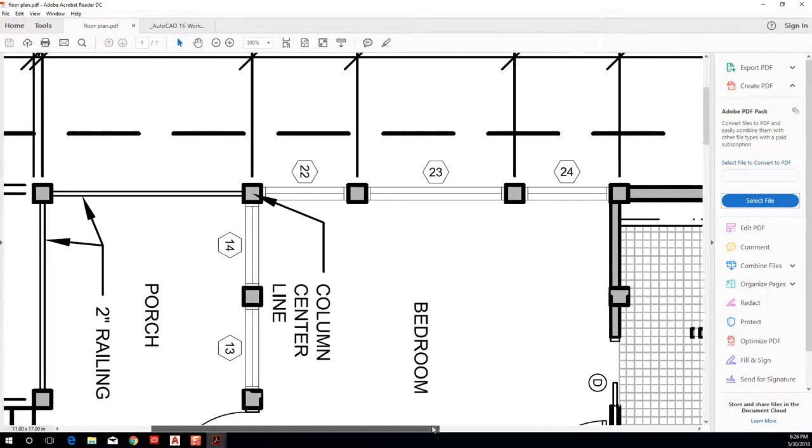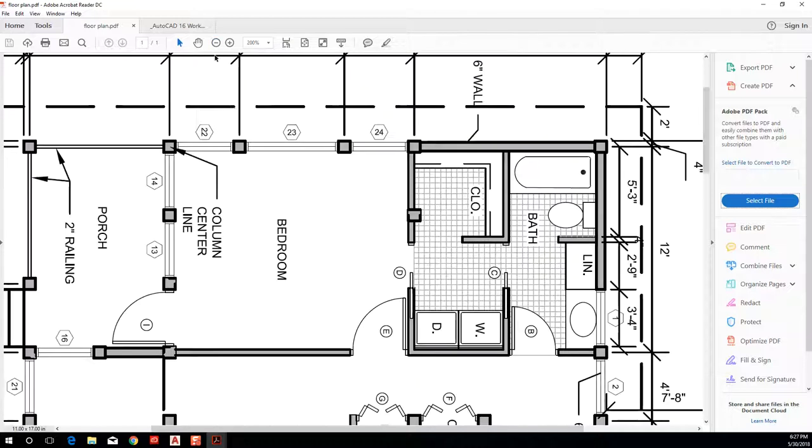I think you're hopefully getting the gist of this, and then we have annotation, which is kind of a medium pen weight, but we'll come back to that. Very important architectural elements like walls and structure are going to be your heaviest pen weights, okay? Medium pen weight will be secondary architectural elements like doors and windows. The third most important architectural elements will be things like appliances, millwork, and plumbing fixtures, right? Those are going to be a light pen weight. And then we have a fourth category of pen weights, which is going to be shading, right? So things like hatches on the floors indicating floor tiles, or wall hatches that are solid like this, okay?